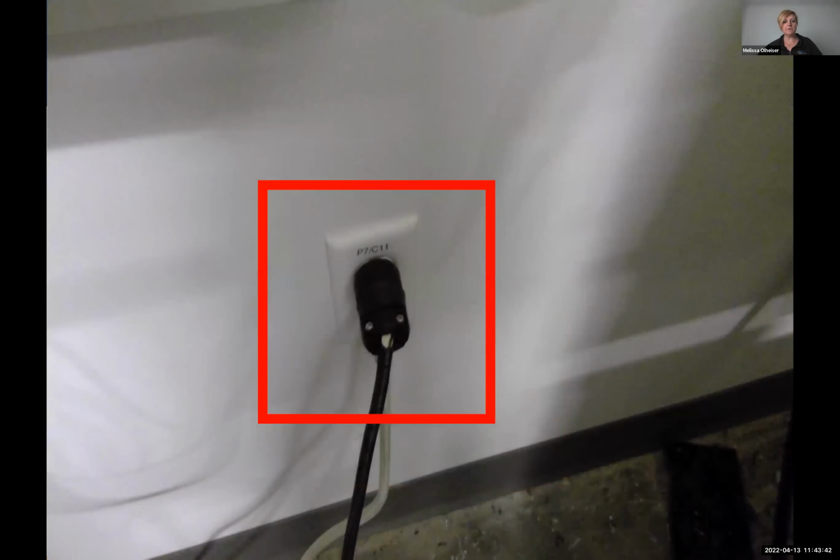All right, the next couple of pictures, just a couple of items that I think get overlooked, and we see them quite frequently, whether in a facility or on a job site, is what's the condition of the cord? Your power cord, your equipment cord, extension cord, whatever it is. And you can see on this one that the conduit's been pulled away from the plug end. But if there's holes or frays or cracks, maybe the ground pin is missing, these should all be removed from service, replaced. So take the time when you're conducting your audit to look at these things, because employees often are not going to take the time.